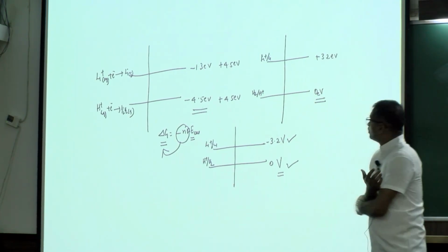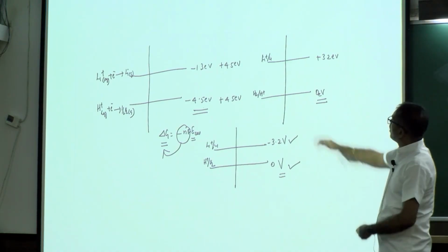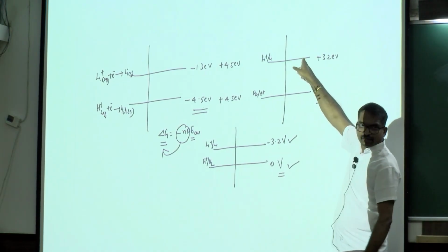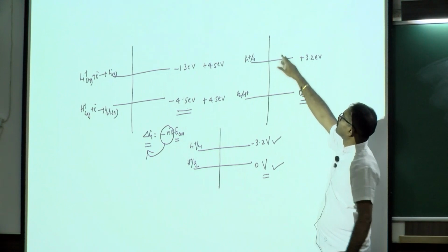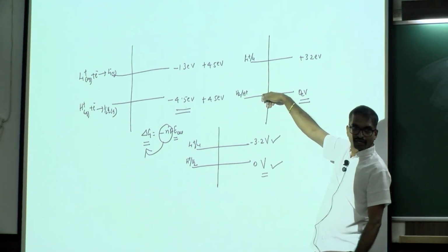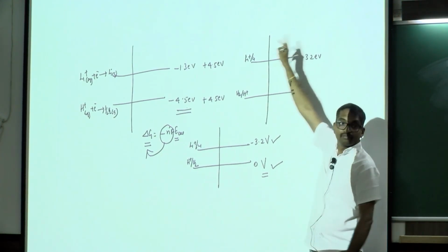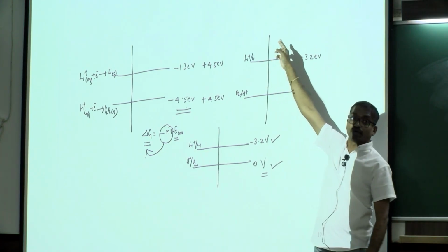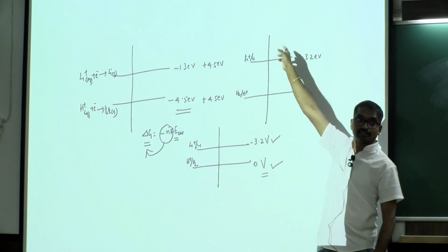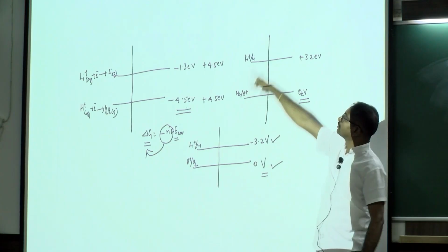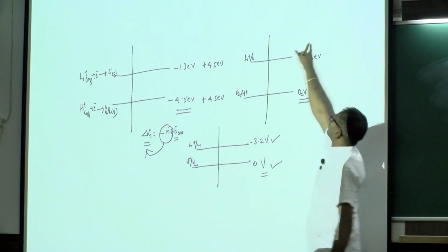Now, the Fermi level is here for this fellow and its work function is smaller compared to this guy, because now the vacuum will get a value of 4.5 electron volt, correct? Earlier it was 0. Now, because I added this, that becomes 4.5, the maximum point here.